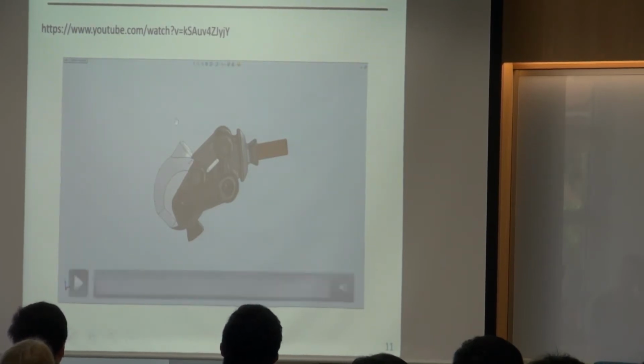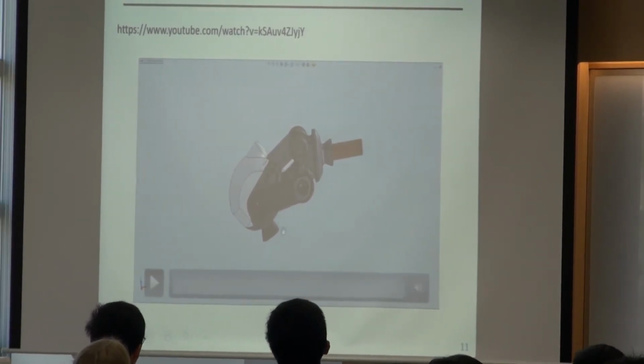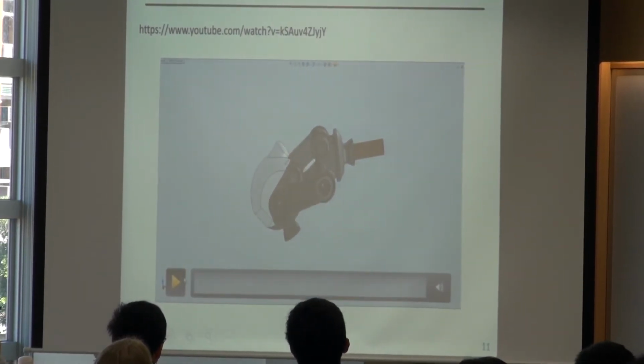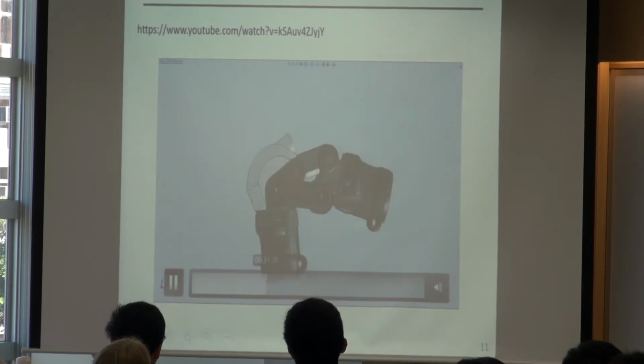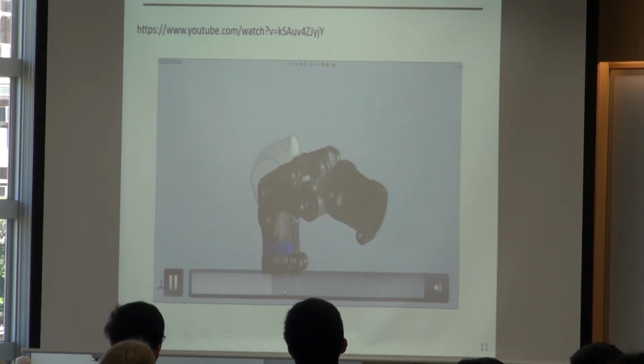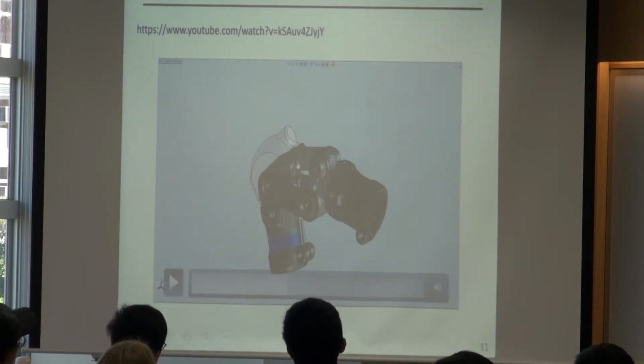So I just found this video on YouTube. I think you can clearly see its motion. So it's basically an artificial knee, and right now it's driving the coupler. So this part is fixed, and this bar and this bar attached to the ground beam. And we are applying force on this coupler.